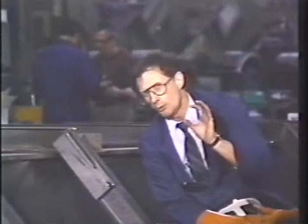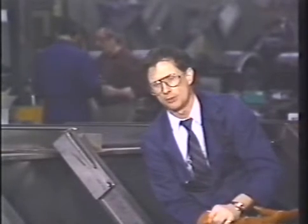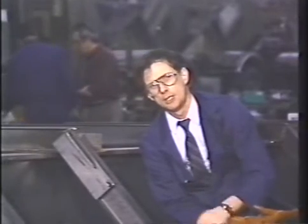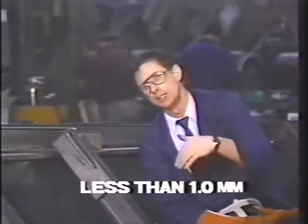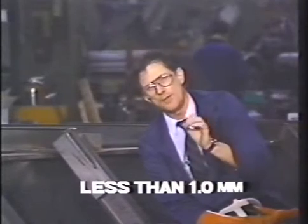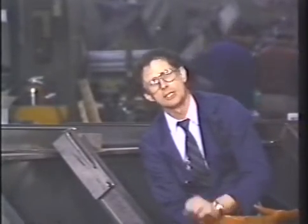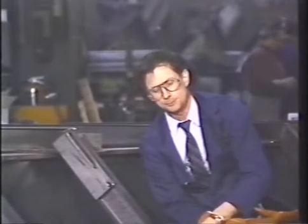But when you get into argon oxygen, you can work at 13 and 14 volts. Again, where should you use argon oxygen? On sheet metal, where you want to weld along the edge of a sheet metal, say less than 40 thou, you will find it extremely beneficial to use 98% argon, 2% oxygen.